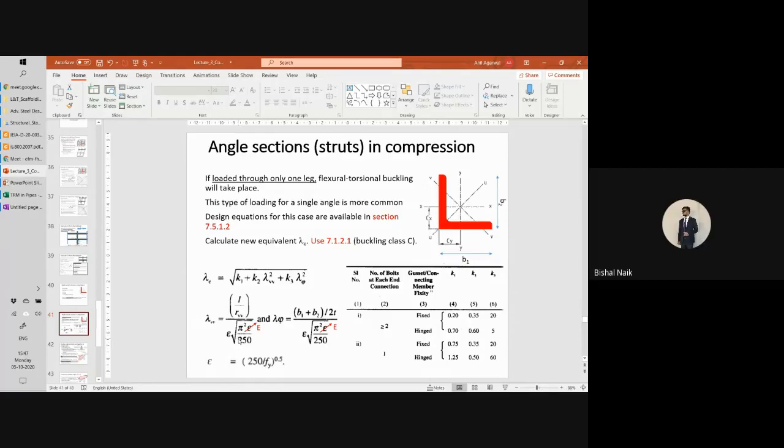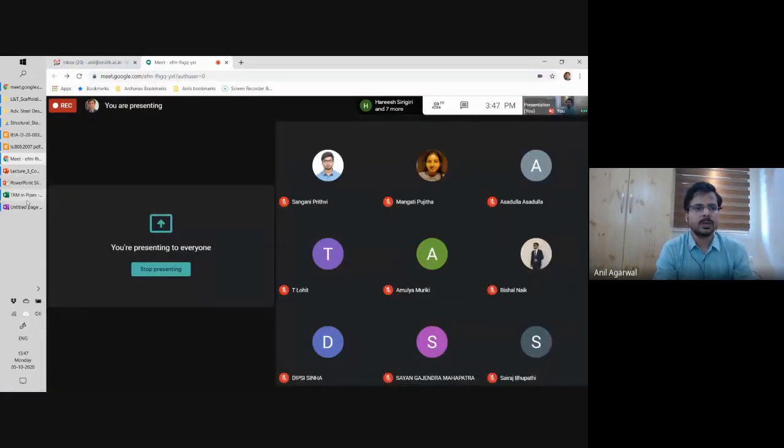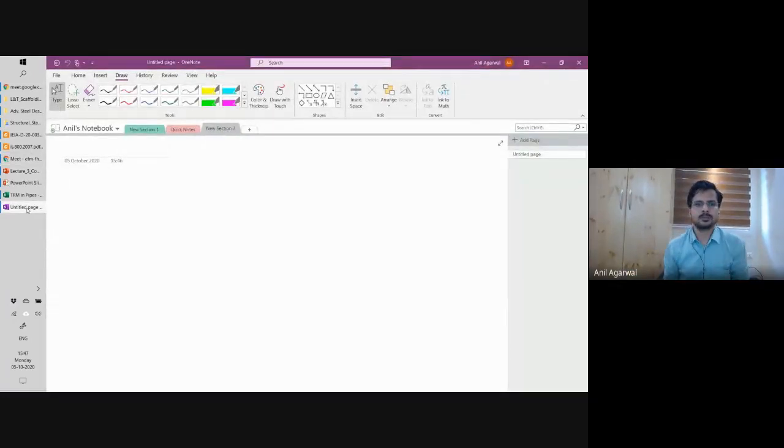Coming back to this question then, tubular sections can be used. I have seen tubular sections being used in towers, telecom towers. I have seen their use in roof trusses of high important structures. I have never seen them in industrial buildings. I have seen them at airports, and in stadia. I'm talking about hollow tubular sections only, not the concrete filled kind.